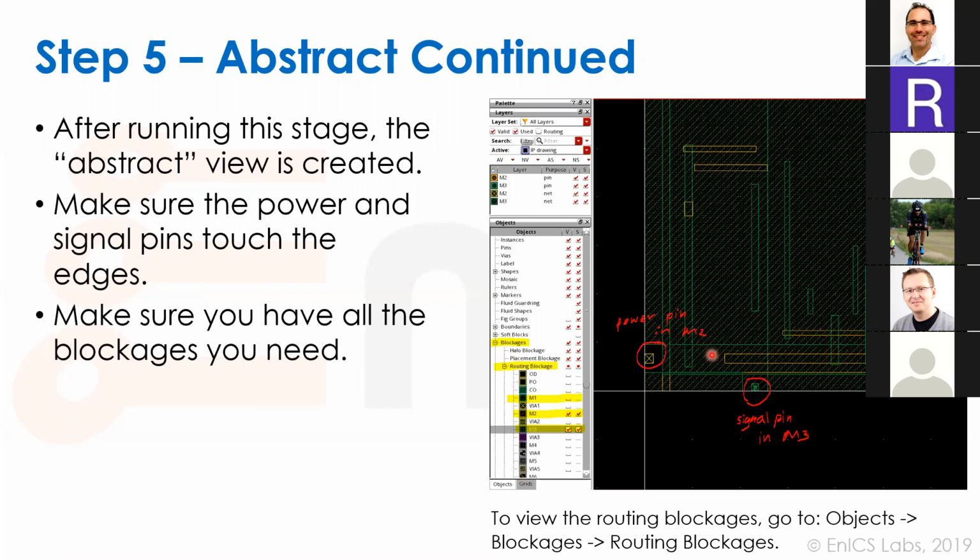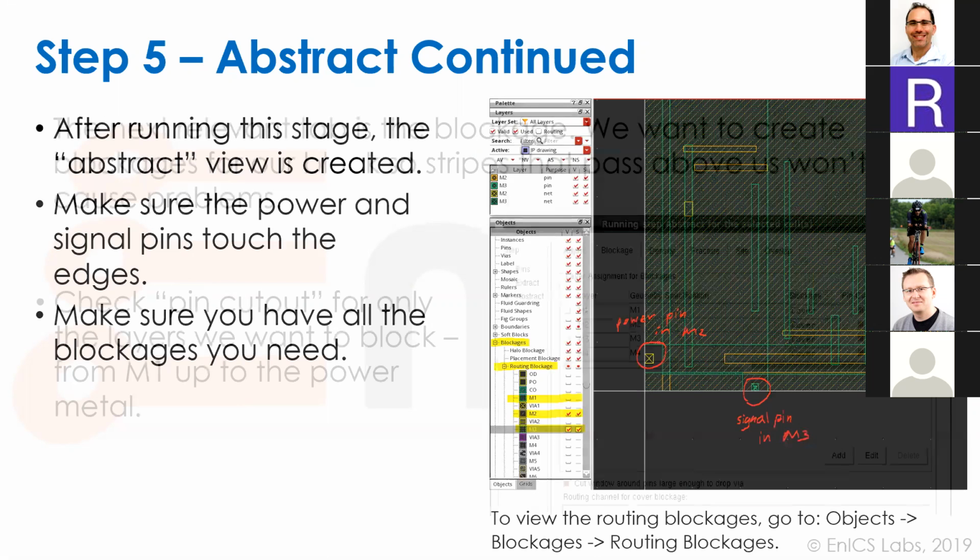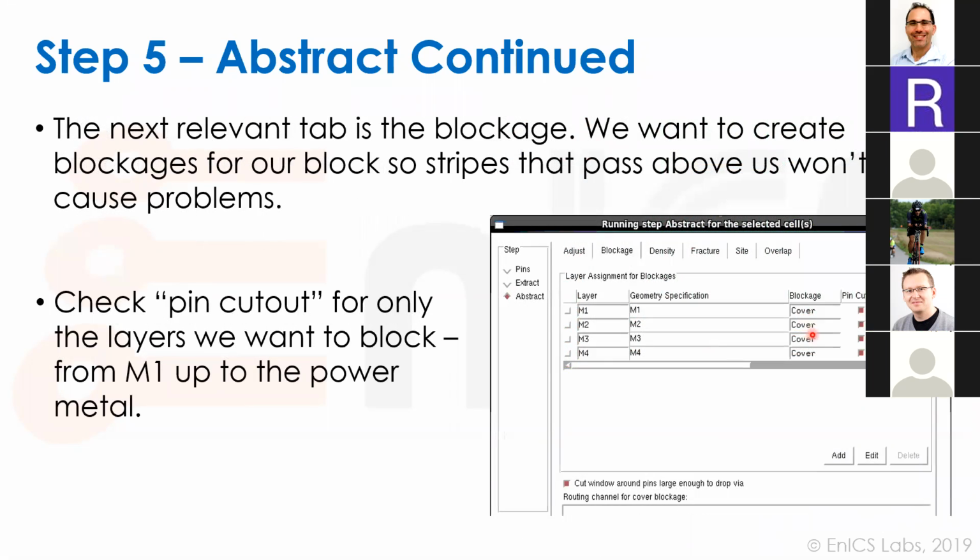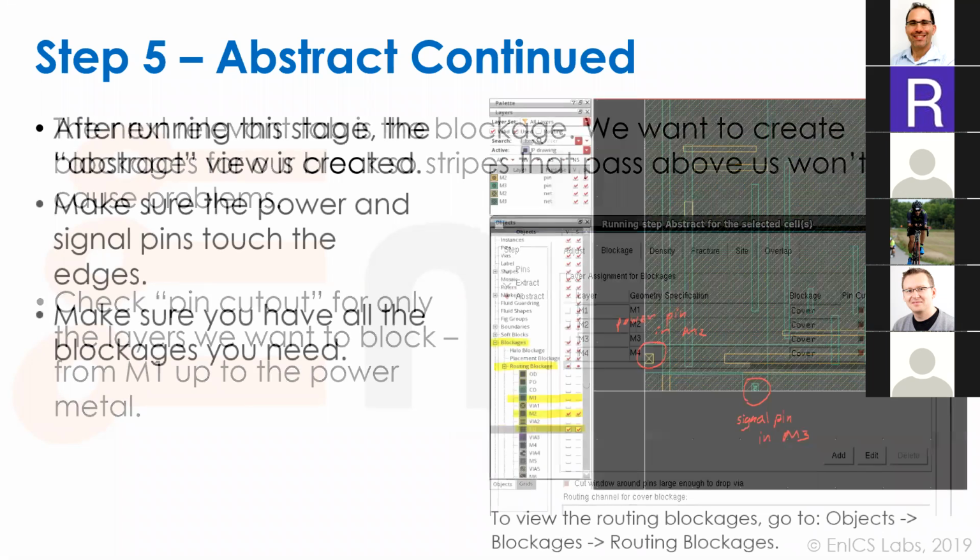So wait, do you hear me? Yes. Okay. So, for example, these green stripes and the yellow stripes inside, I don't need them. This is not good. Beyond that, you see that the pins have some enclaves, some cuts on the edges, right? So if you do a cover there, I think these cuts are going to disappear, but the router will still be able to connect.